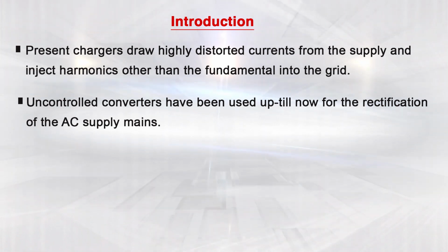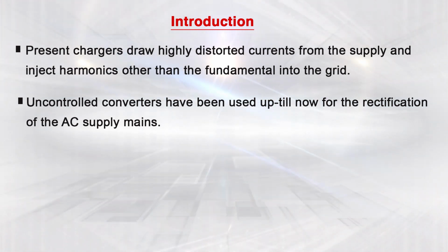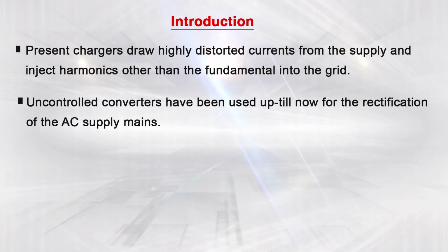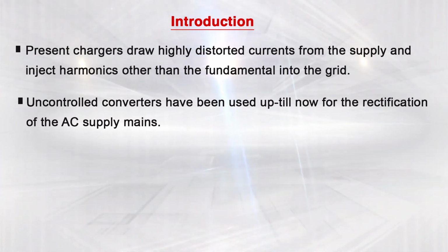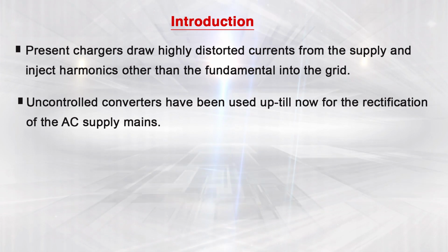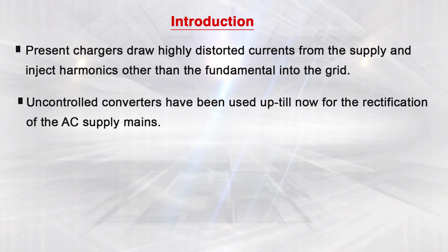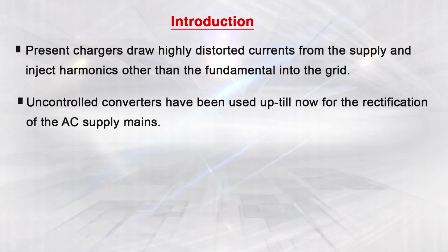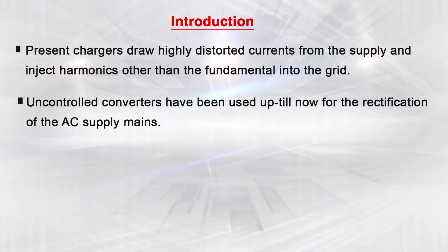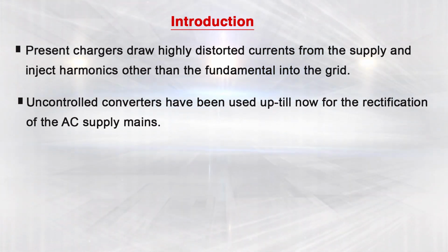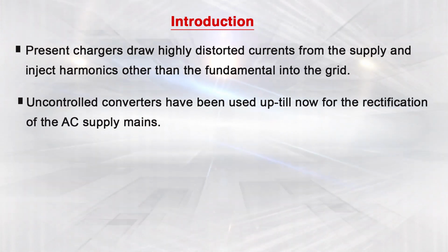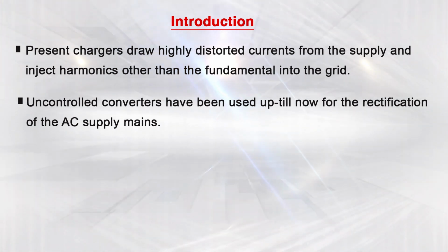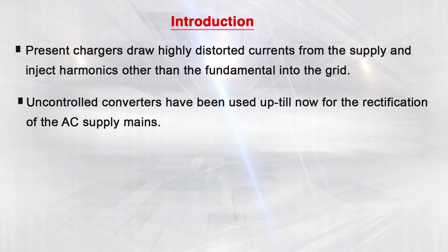Generally, in the case of a charger, one can see we have a capacitor, and before this capacitor we are using one rectifier which is converting AC into DC. So, most of the time in an electric vehicle charger we have this kind of configuration. If you observe the waveform at the input of this rectifier, it draws peaky current.